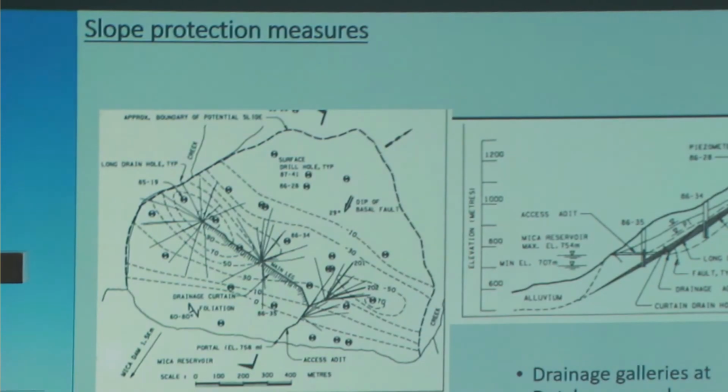That's slope anchoring. And another one I will say is the same thing, and it works with slope anchoring, but we break the kinematic feasibility of the whole rock structure, like the joint and foliation plane structure. We add something and then we break the feasibility. And another is breaking the moment along the shear plane, where we can introduce, let's say, toe support or even increase the load at the toe. There are different things. So I have some examples.